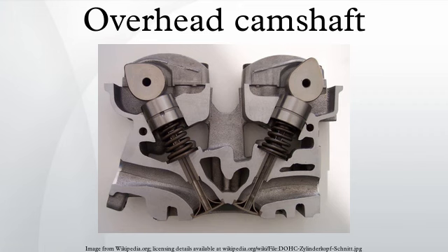given torque. The OHC valvetrain system may be driven by the crankshaft using the same methods as an OHV system, but in practice, lighter weight and maintenance-free methods are more commonly used. These methods include using a rubber Kevlar tooth timing belt, duplex or single-row roller chains, or in less common cases, gears. Early Ducati motorcycle engines used shafts with bevel gears to drive the camshafts in their OHC engines.